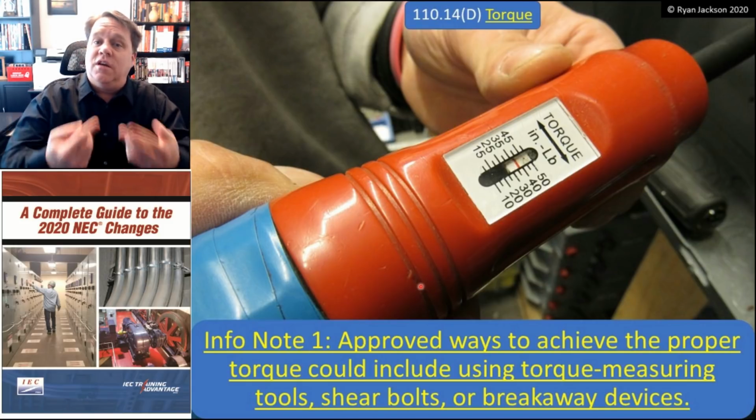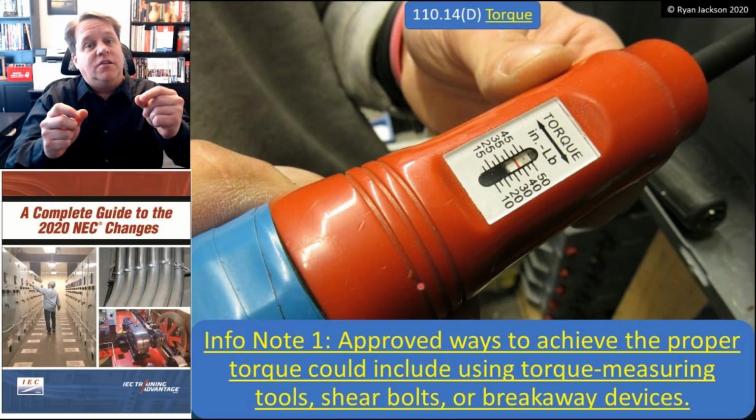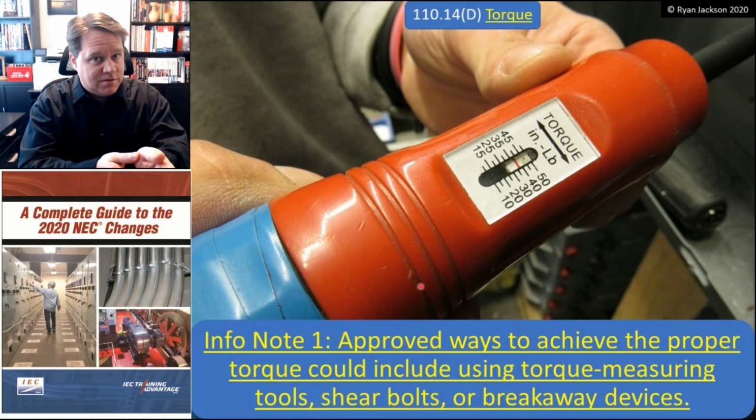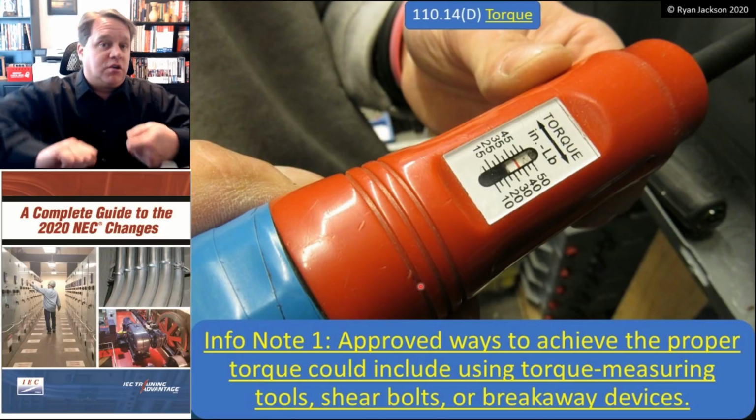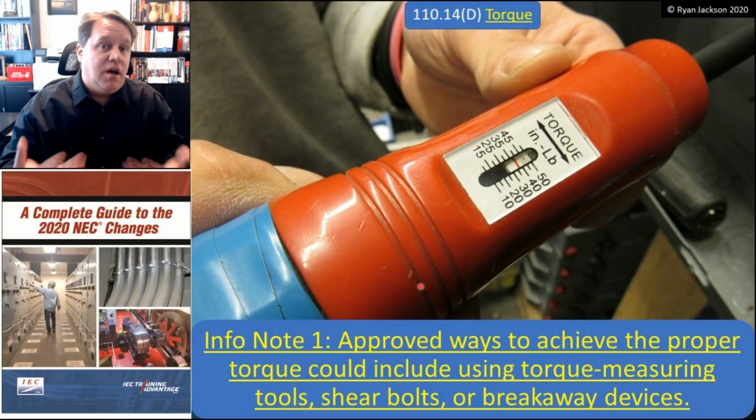And the reason that he knows it's not done correctly is that little nub snaps off when it's been tightened appropriately. So then we know we don't have to measure it. The iron workers can just crank it down until it snaps, and then we're good.